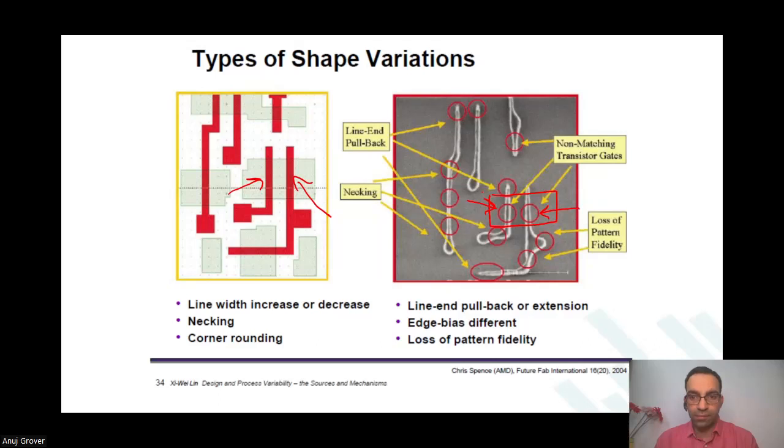Okay. So these are systematic because we can model them. Yes, we can model them exactly. I can tell you that the left device will have more current than the right device, because I can always say this through the modeling and simulation that I did. These are systematic variations. Random variations would be, for example, as we will look at in the next few slides, doping variations.